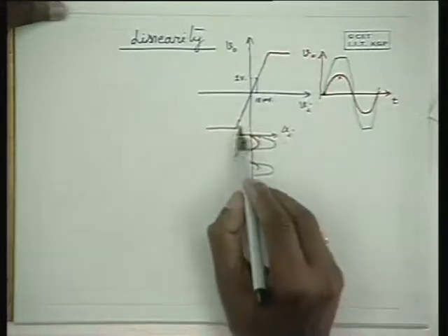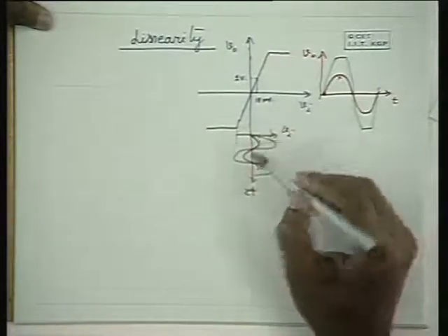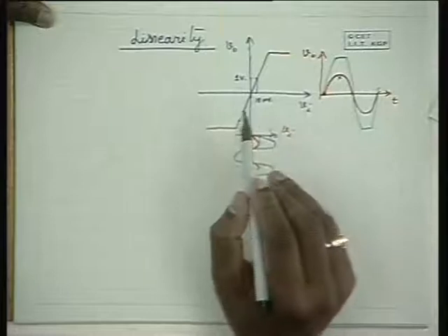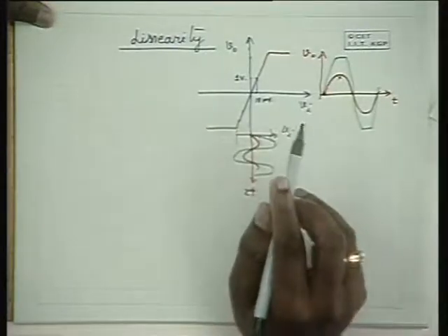Now the question is, can you apply any amount of signal to the input of the amplifier? And please note that the amplifier circuits are made out of transistors. A Q point is selected, and you like to operate it in the active region, and the sources which we use typically are of the order of 10 to 12 volts.